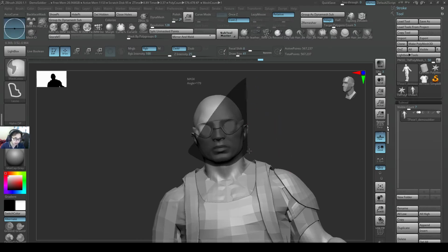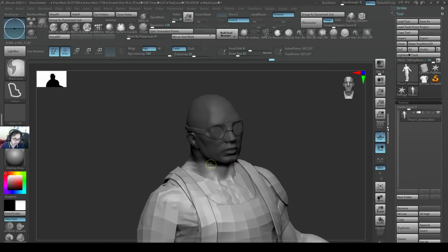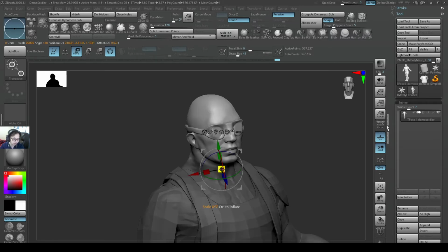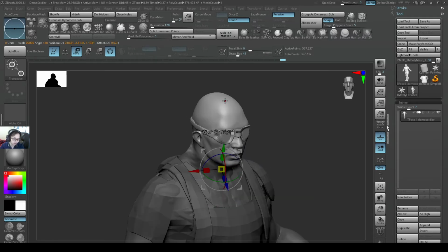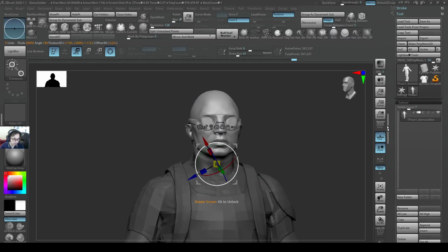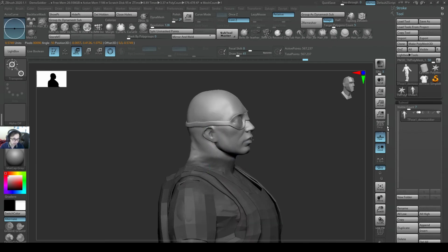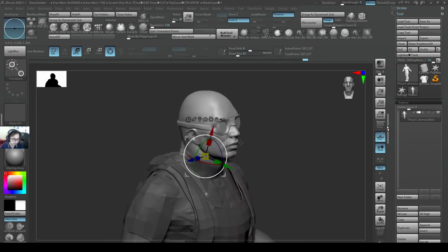Okay, so maybe I will end this with another rotation on the head. So Control left click and Control I to invert, turn it, left click. All these have been taught to you before: different parts of adjusting the model or the orientation of the pivot, how to move the pivot, holding Alt, having this thing unlocked, things like that.